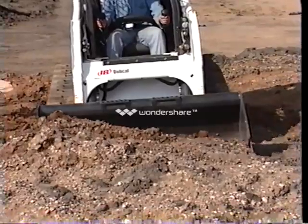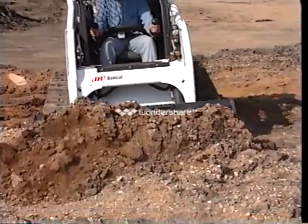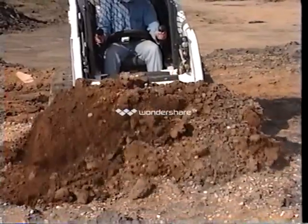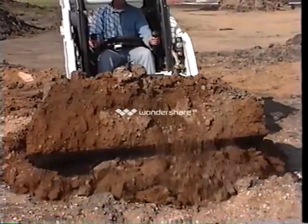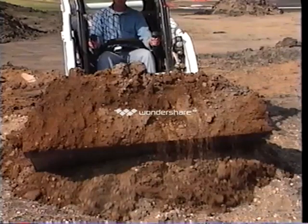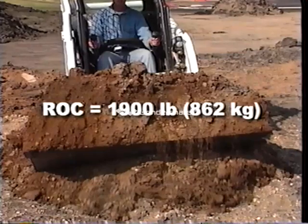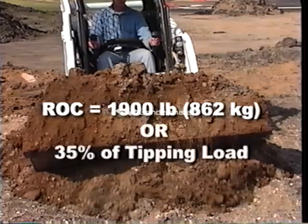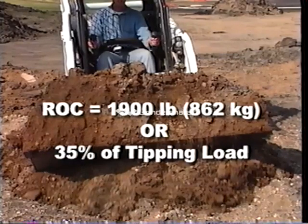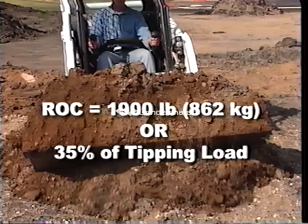The rated operating capacity of a compact track loader is 35% of its tipping load, as opposed to 50% for a rubber-tired loader. For example, the rated operating capacity of a Bobcat T190 compact track loader is 1,900 pounds or 862 kilograms, 35% of its 5,430 pound or 2,463 kilogram tipping load.